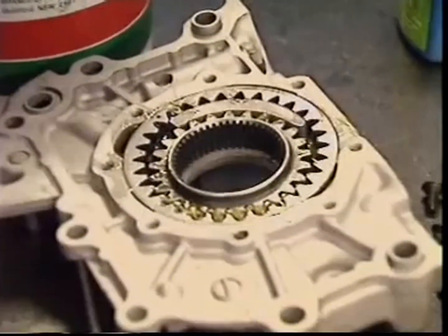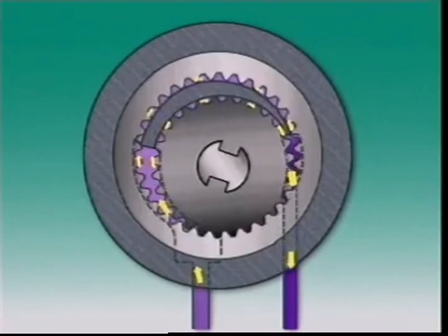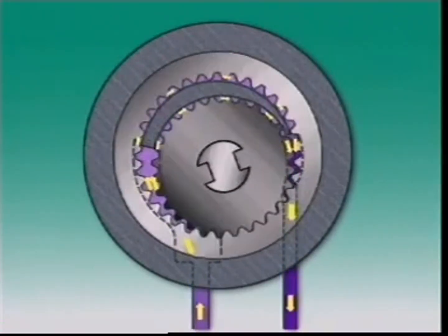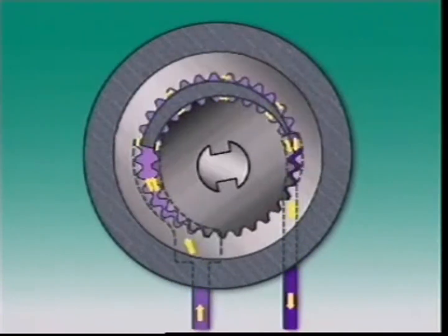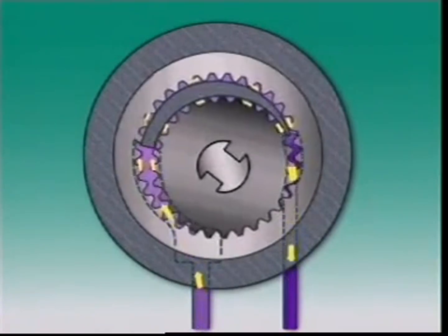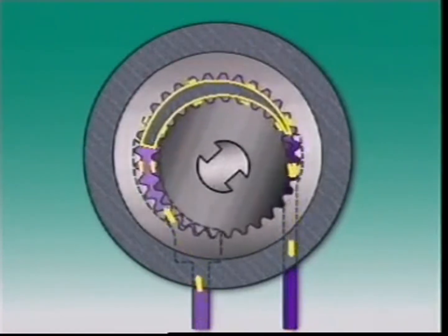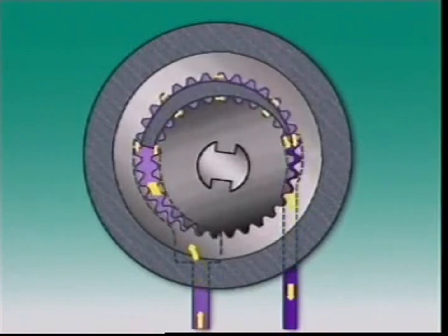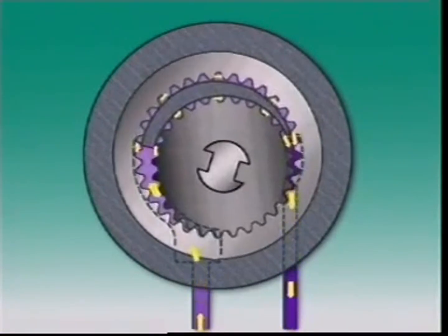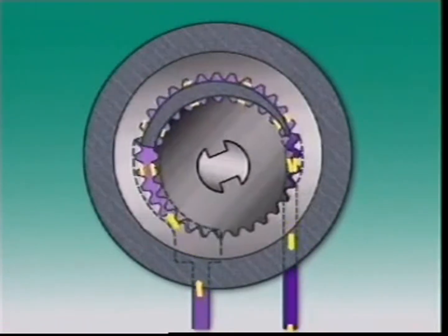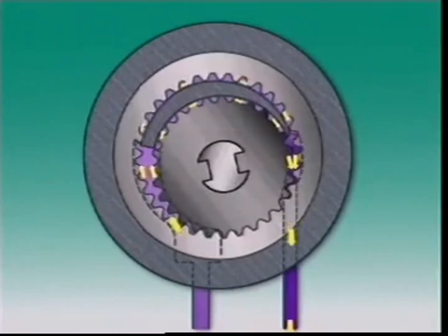It is mounted on the front of the cylinder block. The inner gear is on the end of the crankshaft, which then drives the pump directly. An external toothed gear meshes with this inner one. Some gear teeth are meshed, but others are separated by the crescent-shaped part of the pump housing. The increasing volume between gear teeth causes pressure to fall. Oil is then taken through the intake port and carried around between the gears and crescent, then discharged to the outlet port.